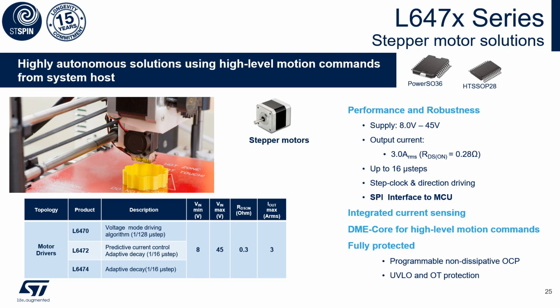The L647X series is a highly autonomous stepper motor driver solution with 3 part numbers dedicated to applications like ATM and money handling machines, medical equipment, antenna control, pick-and-place machines, and home and factory appliances. Those 3 part numbers can be seen in the table on the left side. The L6470 offers an advanced voltage mode control up to 128 microsteps for a smooth and very silent motion, ensuring a performance similar to a BLDC motor.